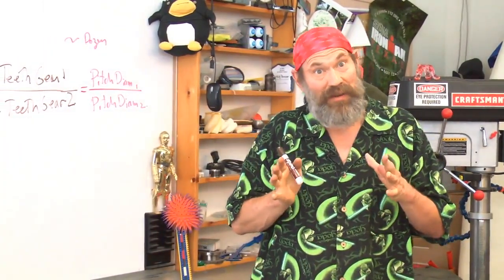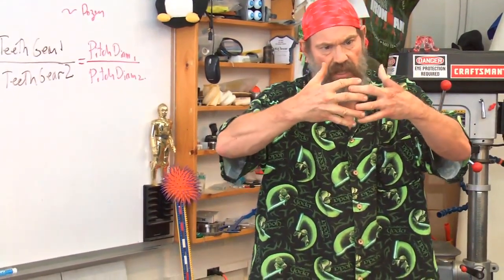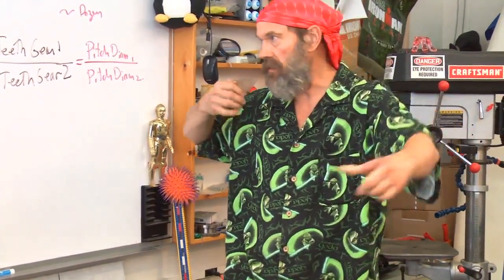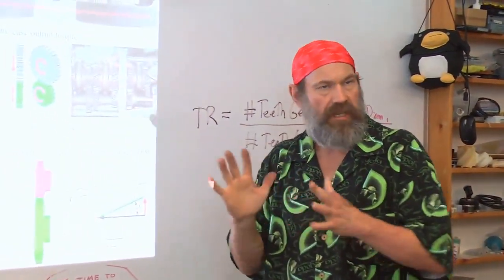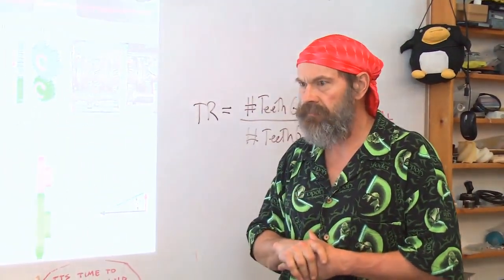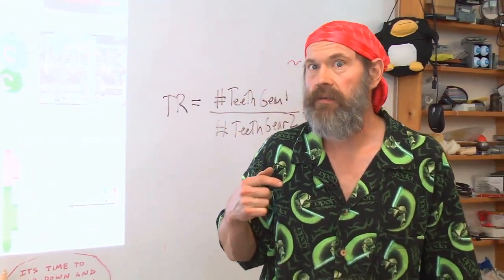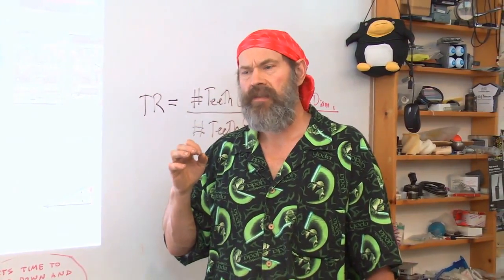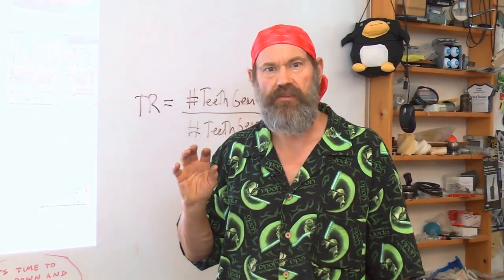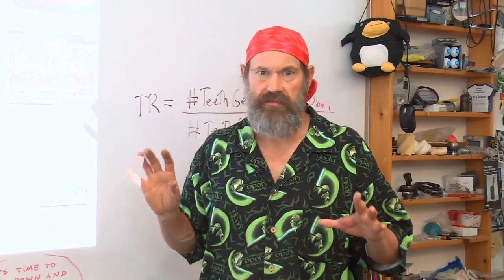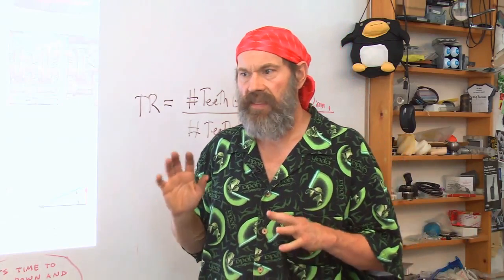But remember we were talking about the pressure angle? One little interesting fact with helical gears, as they engage, they want to push each other apart axially. So you have to design the bearings to support them to take those additional axial loads. It's a real problem. Therefore, it could be a real opportunity. As a matter of fact, it turns out that there's something called a torsion differential, self-locking differential, no electronics. It's what's used in what they call quadratrack drives. And that is an invention